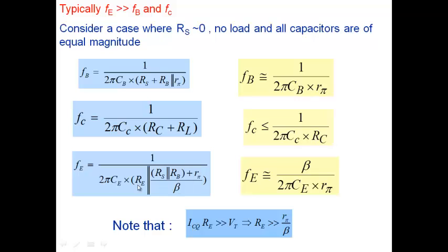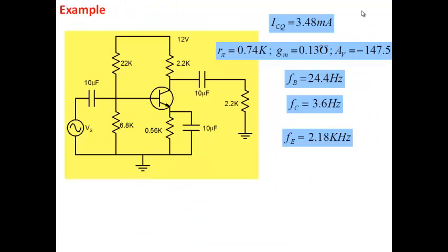Now similarly, you can go ahead and look at what if you increase RE. Say this is not the limitation. Say R pi is still very large. RE is the limitation here. What will happen then? Make RE large. What will happen due to RE large? If I make RE large and you don't touch collector current, right? Collector current is as it is. Then this drop will increase. And what will be the effect of increased VE? The swing is going to decrease here.